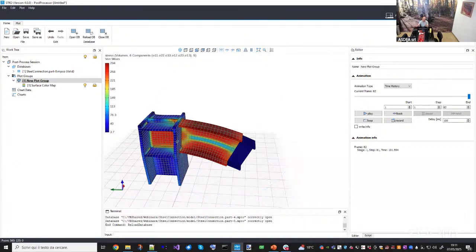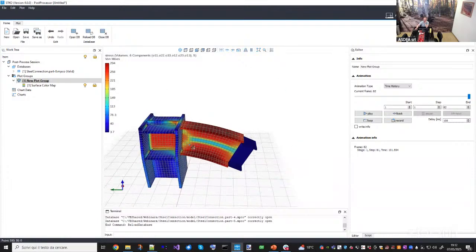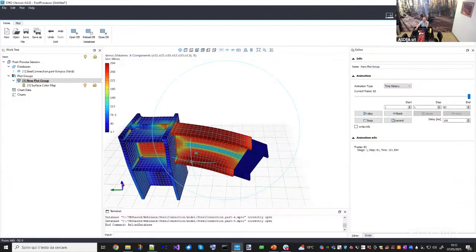We are just going to, okay, so let's combine three things at this point. I will show you how to use shell elements instead of solids, and how to use bolts made with beam elements and fiber sections. So you will be able to see a complete and coupled nonlinearity in the bolt, because when it plastifies in tension and it goes in shear, for example, you have coupling between the nonlinear Dowell effect there. And the nice thing with the bolts made with fiber elements is that you can also apply pre-compression if you need it, and it's very easy in a fiber-based section.